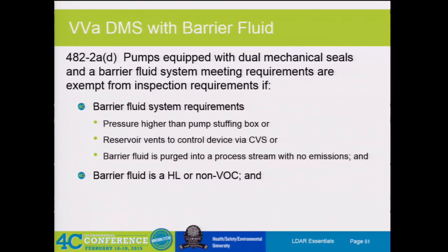That's one way of doing it. You can have an actual alarm that goes to your DCS system that'll tell you if it's lost its seal or not. All those good things are ways to determine if it's lost its seal or not.